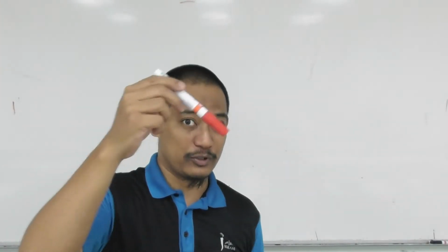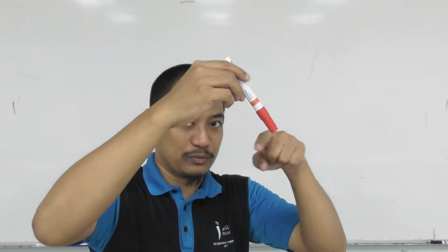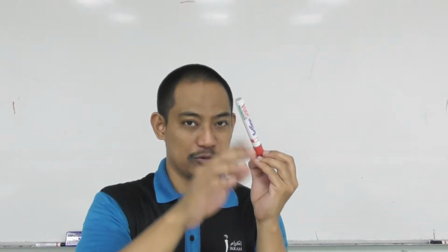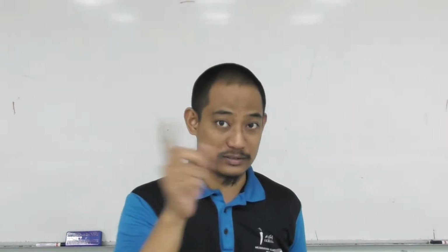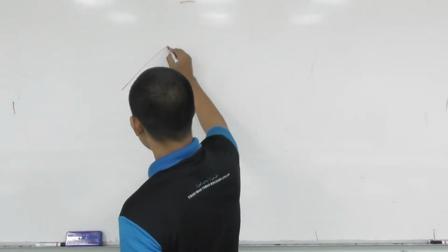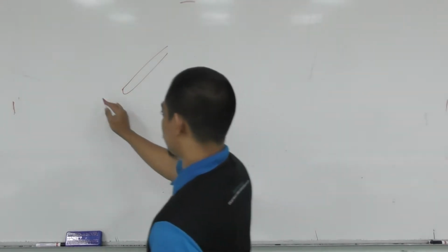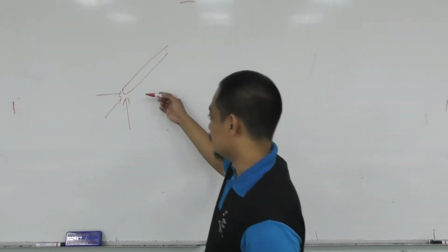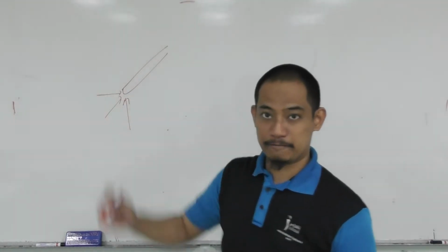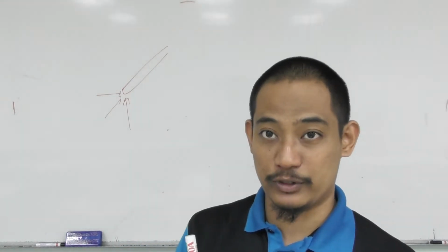So when you draw the free body diagram, you have to draw the X component, Y component, and Z component of the support reaction. And then, does it restrict any moment? Does it restrict rotation about the X-axis, Y-axis, and Z-axis? You can rotate all you want, so it does not restrict any moment. Hence, when you draw the free body diagram in 3D, you just have the three support reactions in the X-axis, Y-axis, and Z-axis. That's how you draw the free body diagram.